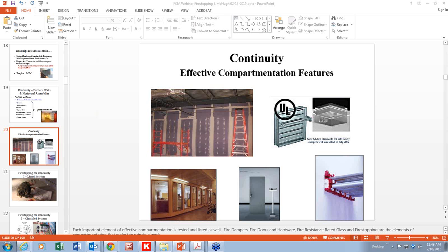That's me personally. Will an AHJ let something else be used? I'm not sure. I don't think they should, because the test standard already exists for an air leakage rating, and they should stick with what the test standards are, UL 1479, UL 2079, and ULC S115, with the smoke resistance. That smoke resistance is specified as it's got a test method for it, and it really needs to be used. Really great question, Saifuddin. Thank you for asking it.